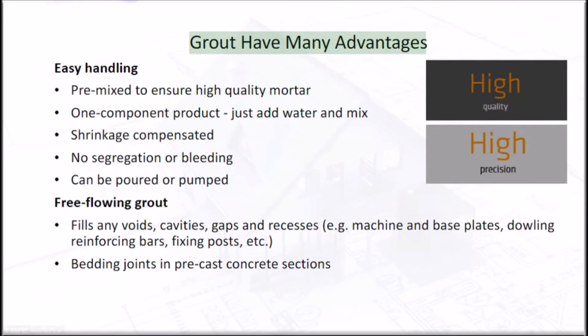Grout has many advantages. Easy handling. Pre-mixed to ensure high-quality mortar. One component product, just add water and mix. Shrinkage compensated. No segregation or bleeding. Can be poured or pumped as free-flowing grout.